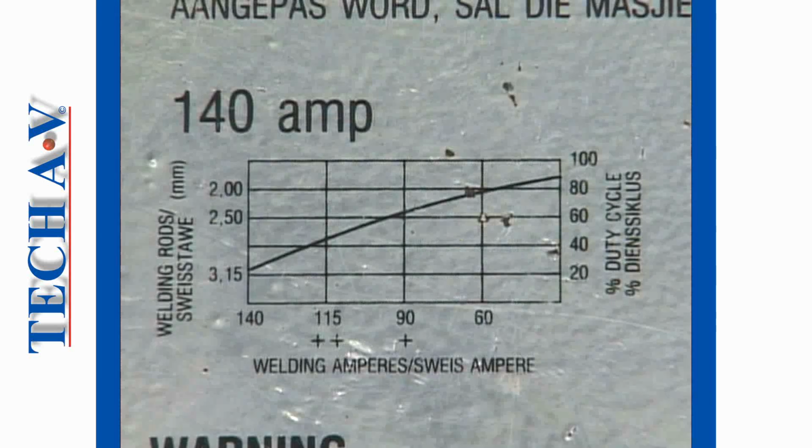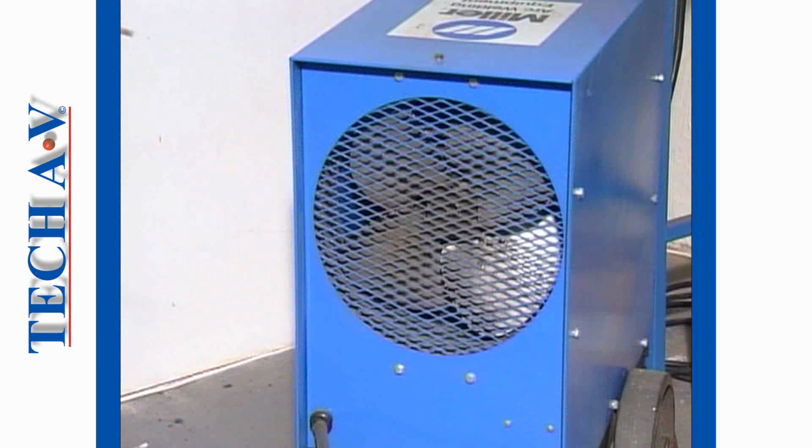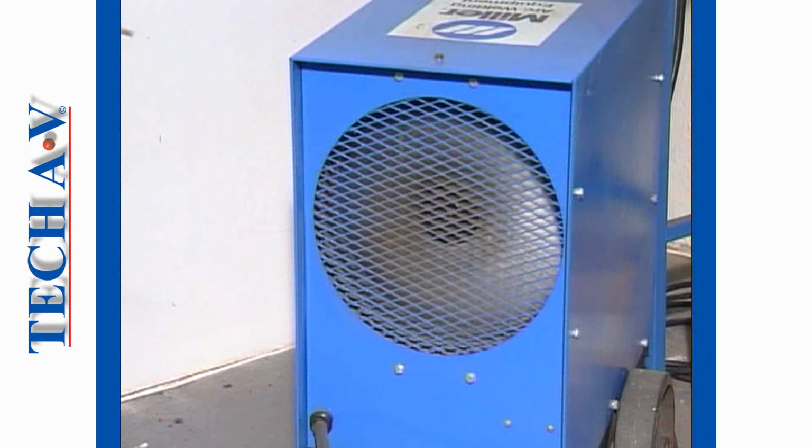Most manufacturers supply either a duty cycle graph or print duty cycle information somewhere on the machine, from which one may determine the duty cycle at a given output setting. Note that some machines employ a cooling fan. The fan operates only when the machine is switched on. For efficient cooling, such a machine should remain switched on during the cooling periods.